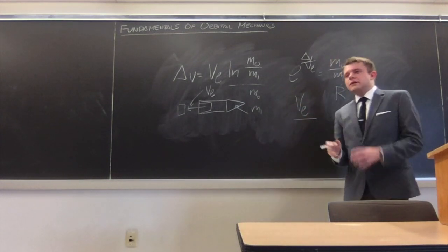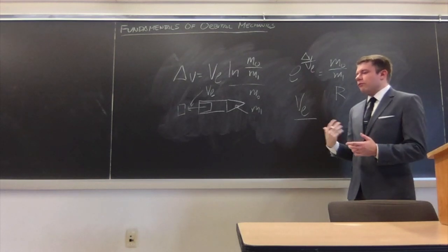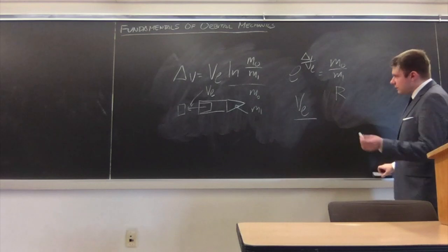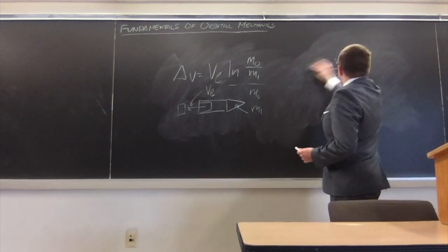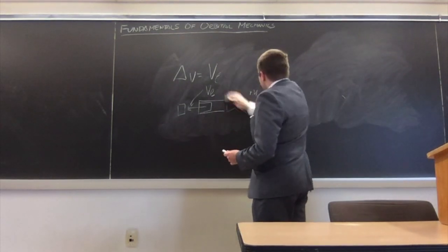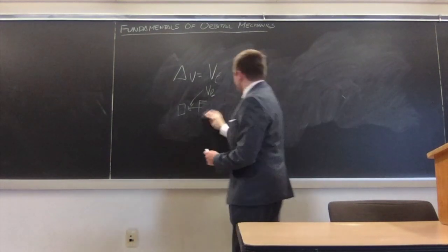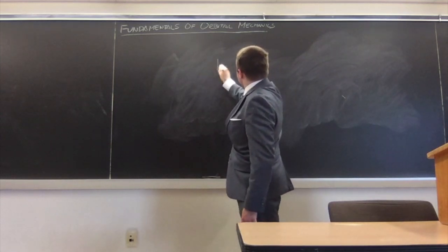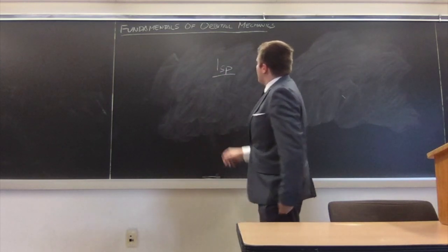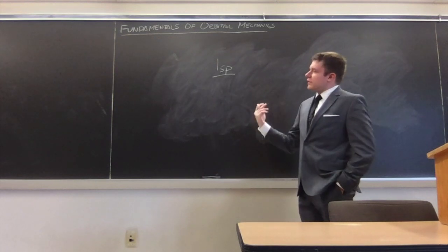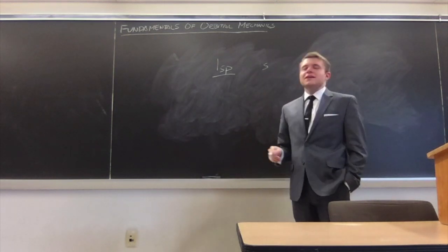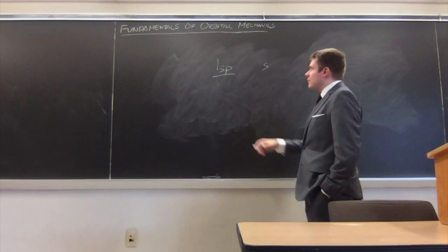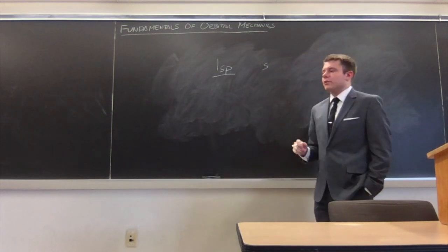Effective exhaust velocity comes into being because of the way that rockets are categorized. There's this concept called specific impulse, and I'll clean off the blackboard as we walk into that. Specific impulse is basically an Earth-centric means of dealing with the performance of rockets. You may have seen this before, but it looks like Isp. The reason it's called specific impulse is that it has a unit of seconds because of unit cancellation. Because unit cancellation is painful and terrible, and I don't like to think about it very much, we can simply accept this as the word of God.